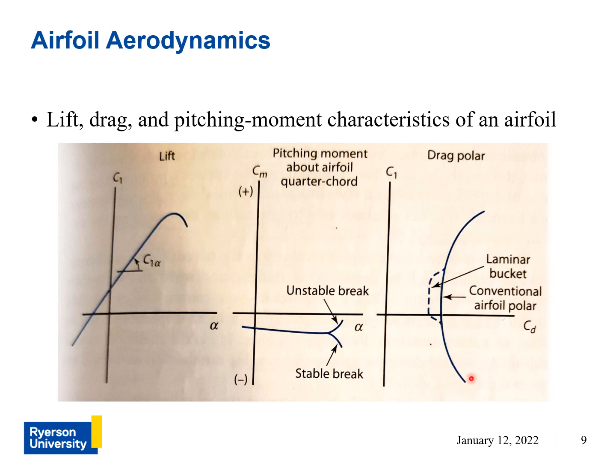The third graph, again, is called the drag polar because of its parabolic shape. We normally plot the drag coefficient versus the lift coefficient instead of the drag coefficient versus angle of attack.